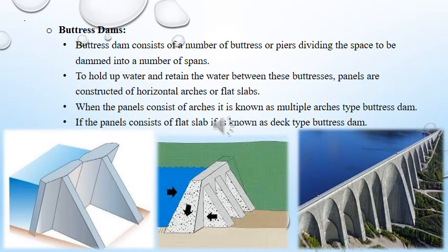Buttress dam. An ordinary concrete gravity dam is a solid body of mass concrete, somewhat triangular in section, running across the entire width of the river. Such a solid wall requires a huge amount of concrete, which partly remains unstressed to full extent, thereby leading to wastage of concrete.